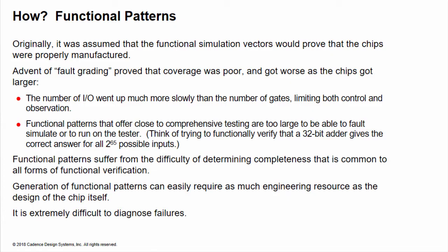Furthermore, as chips got larger, the controllability and observability of logic states within the chip became harder, and more effort was required to create the functional patterns. It's not unusual, even with reuse, to see as much human resource used to generate functional test patterns as is used to design and verify the chip. Finally, it's extremely difficult to determine the root cause of a failing functional pattern. Still, functional patterns are used as a supplement to automatically generated patterns.